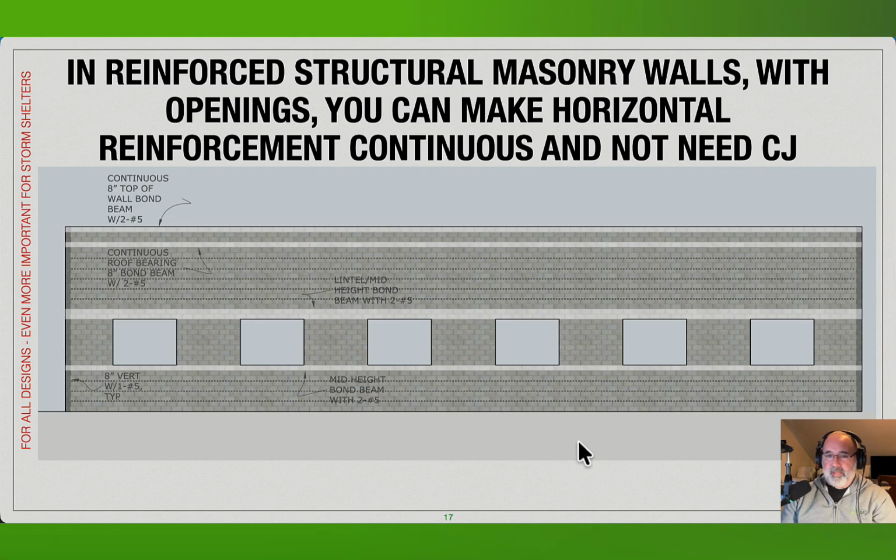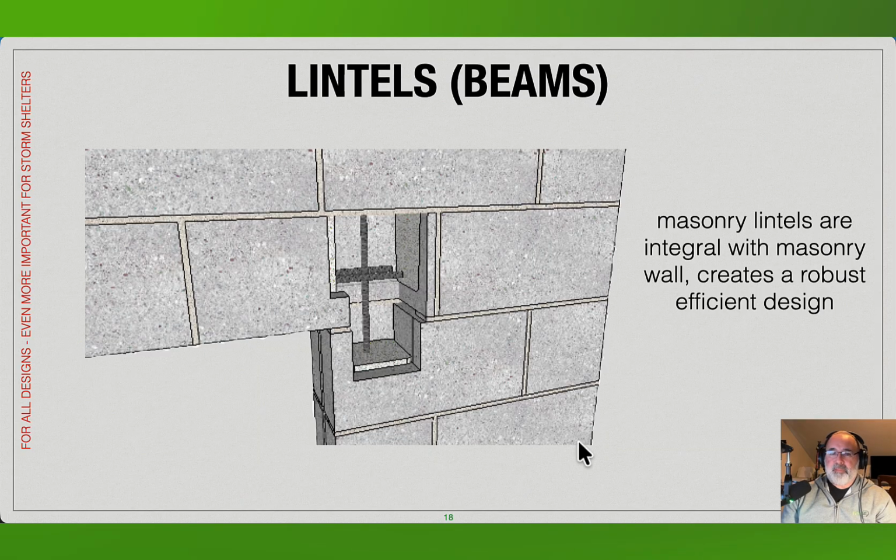But again, the masonry design is also going to change a little bit. We'd have some continuous masonry lintel elements over the openings and continuous sill elements, some combination of horizontal reinforcement to, again, not need to have any movement joints. We have a few different things that are kind of in play here. I mentioned lintels. If we look at masonry, lintels would definitely be the option we would want to go with. It's going to create the most robust elements for spanning an opening.